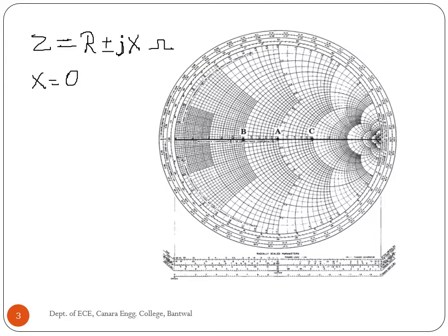In order to make the Smith chart universal, the impedances along the pure resistance line are normalized with reference to system impedance. For most microwave RF systems, the system impedance is standardized at 50 ohm. To normalize the actual impedance, divide it by the system impedance. For example, the load impedance is given in ohm.